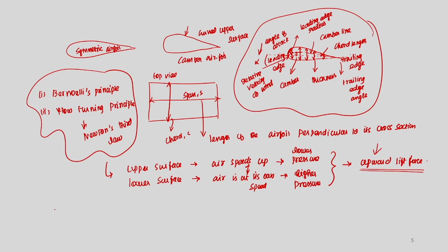So, then after doing all these things, we have seen the wind speed versus height, and we said that the simple formula, which is nothing but V upon V naught is equal to H upon H naught to the power alpha.